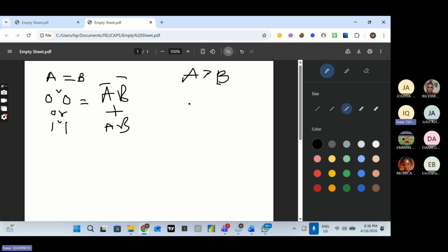When we are dealing with zeros and ones as our A and B, when do you think A will be greater than B? When A is 1 and B is 0. When A is 1 and B is 0, that's just perfect. So in this case, you are going to get A is greater than B. And when A is 1, that is your A. When B is 0, that is B prime. You are done. So we've deduced our logic expression.